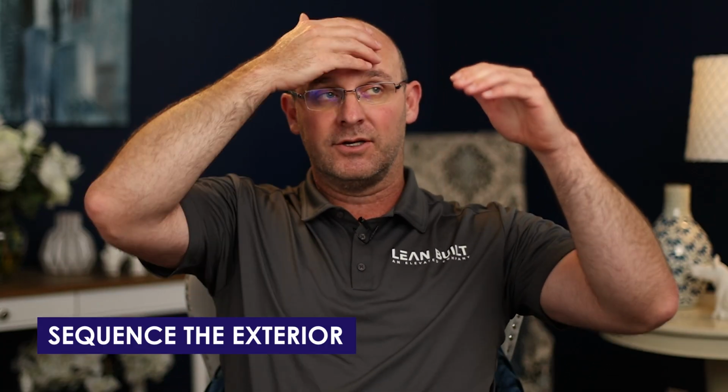I remember a project where the original superintendent, and we took over the job, but the original super said northeast, southwest for the exterior. And that literally would have boxed everybody into a corner and shoved site work literally with no exit. He was like, no, we can't do that. We've got to understand how the exterior needs to install, and we need to exit out on the northeast side. So we were able to do east, southeast, southwest, west, then move over to the northwest, middle, and out the exit, but sequence the exterior to where it was done in time for that to happen. Here's how you have to look at it. The exterior comes down, site work is available.